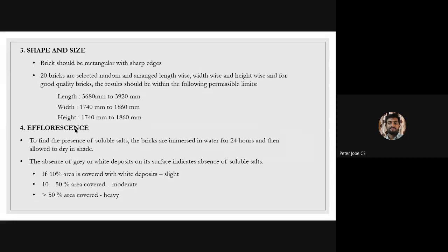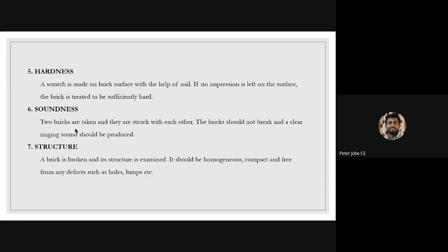So this is a test used for efflorescence. That means we will check the white patches. We'll immerse it in water for 24 hours, and then we will check whether there are white patches on the surface of the brick. So this is the fourth test.